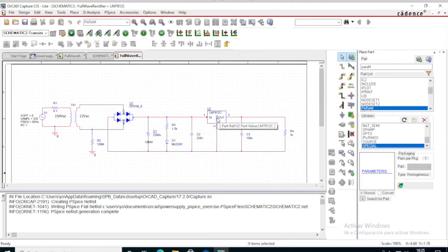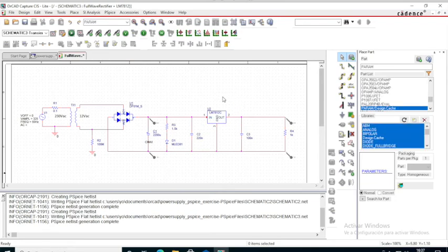Okay, so here the signal is what we showed after the ripple. Here we have the 2200 microfarads, so it's about 16 volts or whatever with a ripple signal, but here after the output is going to be flat and 12 because the regulator has that value. So with this regulator we put marks before in the filter output and after in the flat output of the regulator, so we compare and see that it's working perfectly.